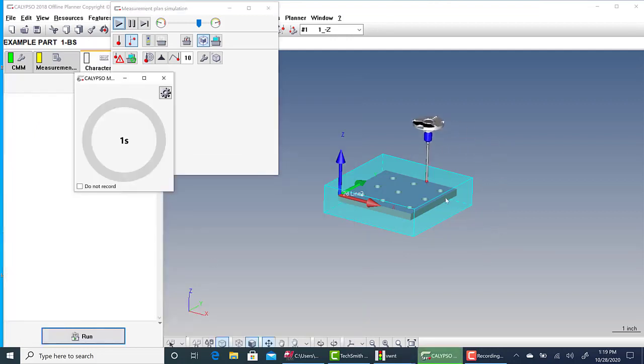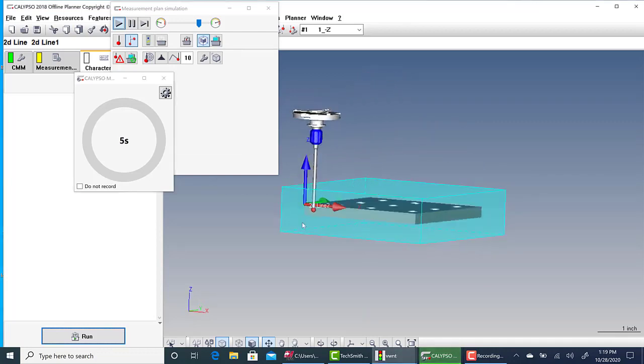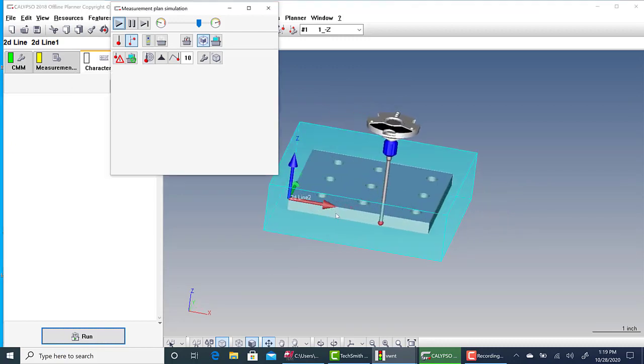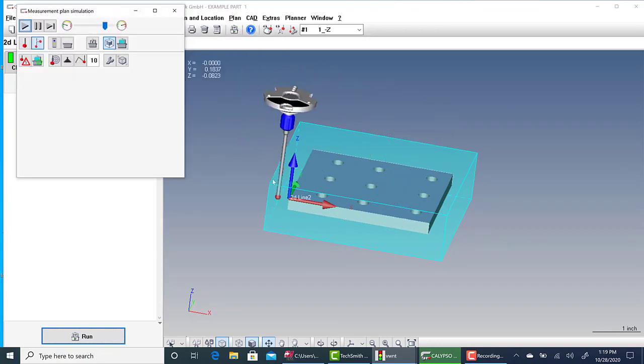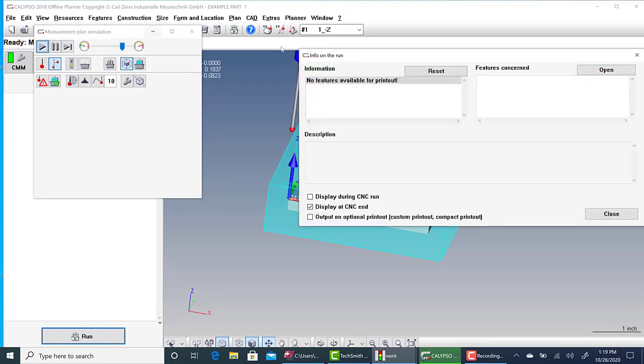And you will see this go through and actually contact the workpiece. Scan this line, or take points. Okay. Again, these machines are full scanning capability, but we'll just take points for these. I thought, off the top of my head, it defaulted, but I did erase all of my default parameters. Because typically there's nothing there. Don't worry about that. There's no features, there's no printout. We just need alignment.